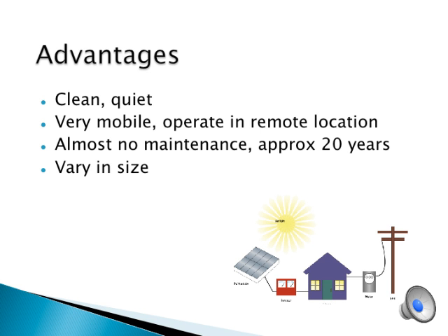String inverter connects one inverter at the end of each PV string. By doing that, it is possible to optimize each string and increase the efficiency. It also reduces the system wiring. On the other hand, string inverters still face a series shading problem. Other disadvantages include high input voltage requirement and PV modules have to have the same orientation.